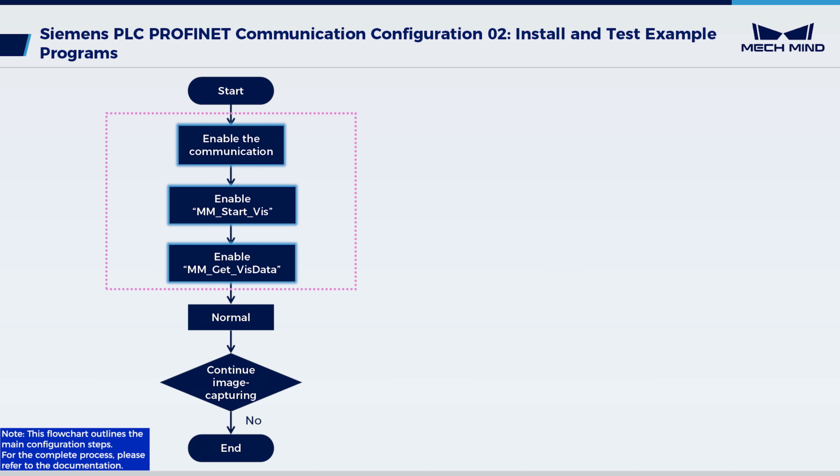When finished, configure the parameters in this function block. Set the Mech-Vision project number to run the specified project. In this case, there is only one Vision project with a number of 1, so set the value to 1. Next, set the number of poses returned by the Mech-Vision project to get the desired results. In this case, all Vision results are required, so set the value to 0.